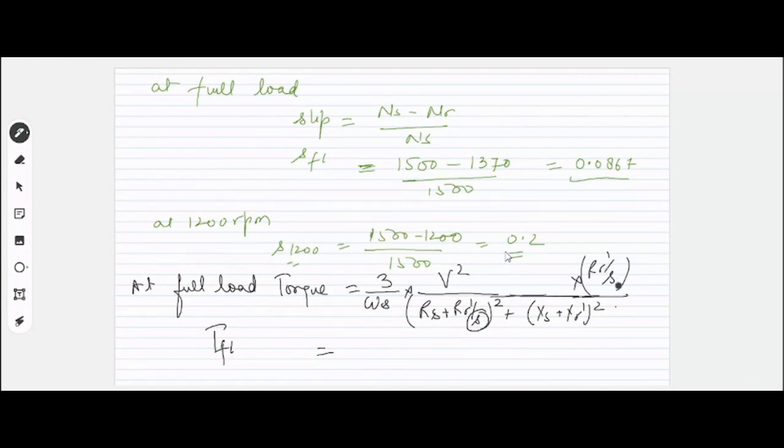So at full load, your slip will be slip at full load, SFL. Use the value of SFL. We know the value of voltage, that is 400 volts, right? We know the value of resistance. We know the value of reactance for stator as well as rotor. So how much will be the full load torque value?